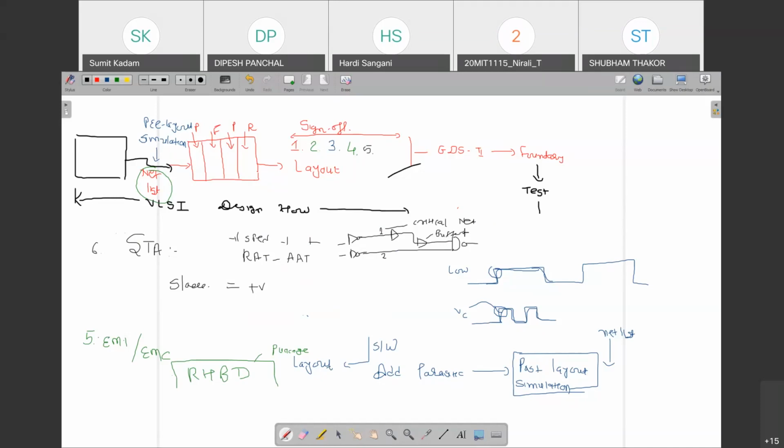That process is also available once we see the Cadence Encounter, how we can perform the static timing analysis. So it's an important checkpoint. If there's a timing violation, definitely you have to avoid that timing violation because you have to meet the required speed of our design. So static timing analysis is checkpoint number 6 of the sign off. Once your design has passed through all these checkpoints, then finally you have to generate the binary file, the graphic data system file, and give that to the foundry.